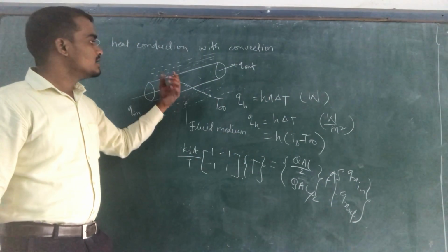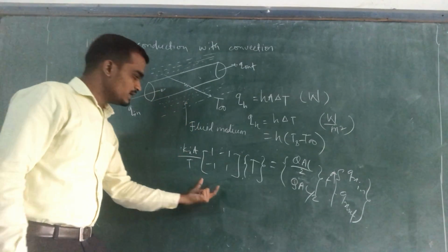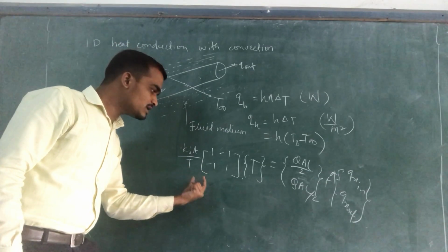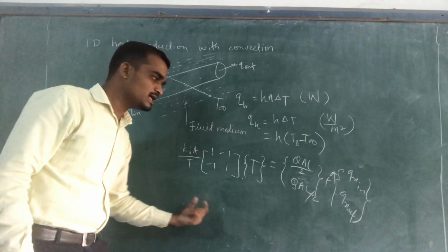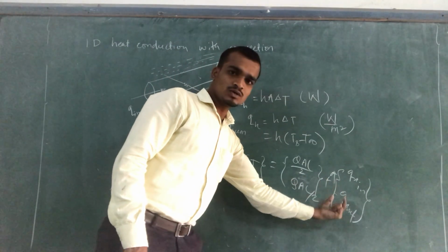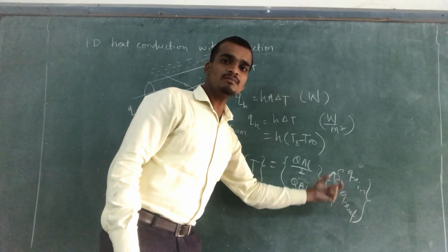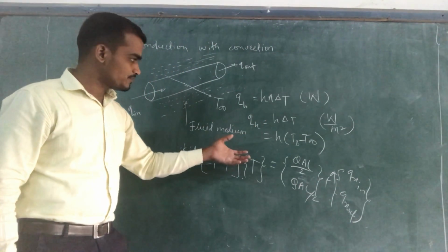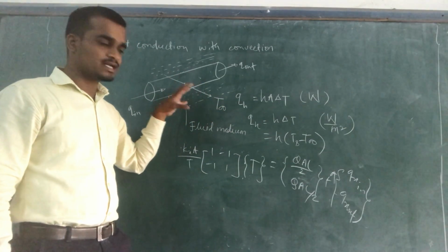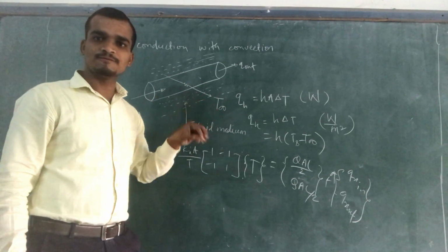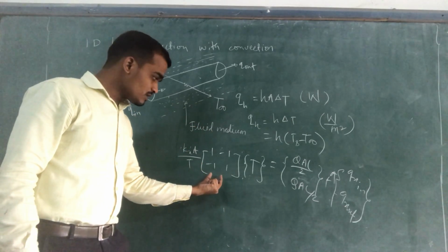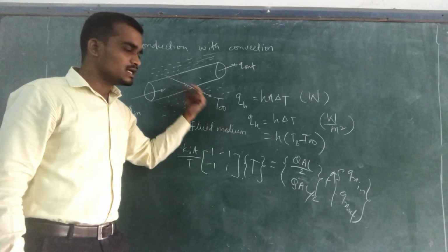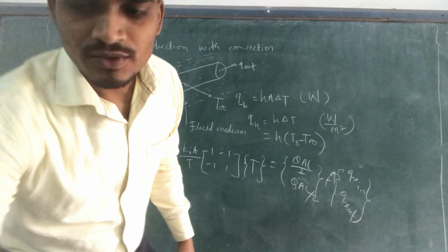Now we are adding the convection effect also. For the LHS side, we need to add one term, that is the elemental convective stiffness matrix. Similarly, we need to add one or two terms related to the convection boundary condition. So we will see how this equation looks, or first we will try to derive the elemental convective stiffness matrix with the help of the governing differential equation for one-dimensional steady-state heat conduction as well as heat convection problems.